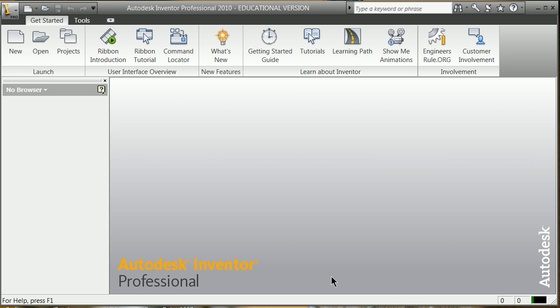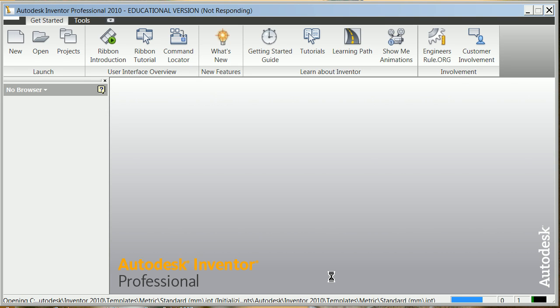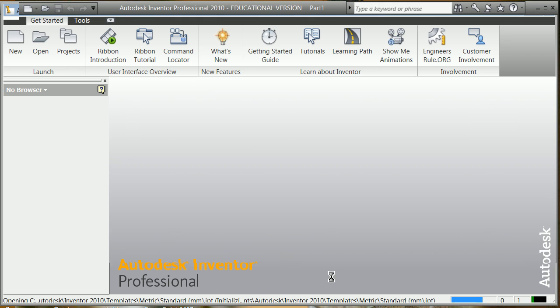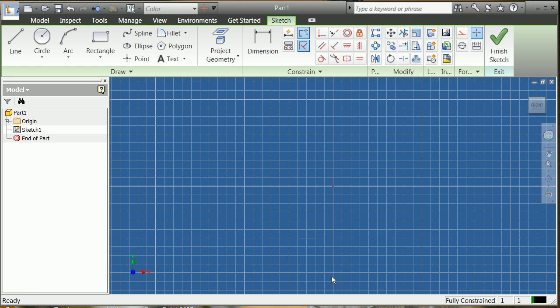This now is going to bring up a flat sketch, which very much is going to be a place where you're going to do something akin to what you're doing in the 2D AutoCAD class or 2D SketchUp if you're using SketchUp. You're going to draft a flat projection of something, and in this case I'm going to make it very simple. I'm going to go ahead and draft a rectangle here, and I'm going to put in a circle right around there.